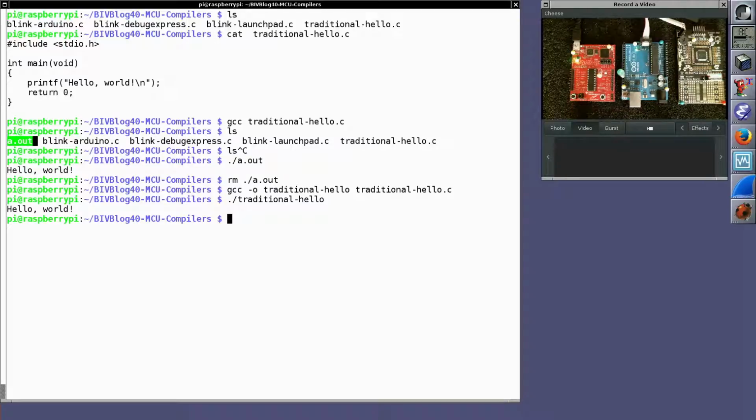And we can do the same with both the Arduino and the MSP430. It'll be slightly different with the PIC board because we need to use a different compiler there. But before we do that, let's do things properly. One thing you pretty much always want to do is enable warnings. Minus uppercase W all turns on all warnings. Always a good thing to do. And minus pedantic.